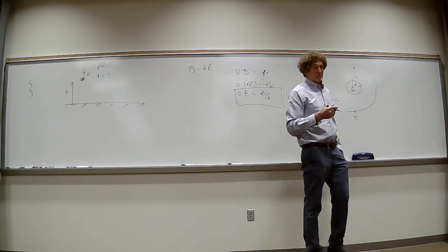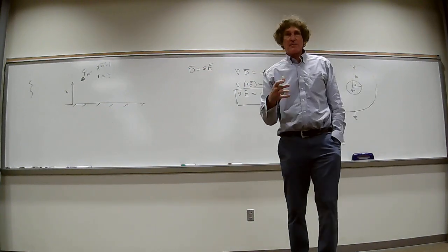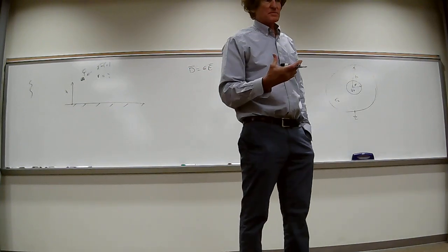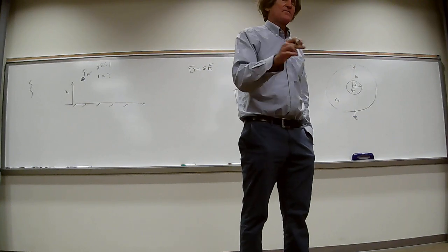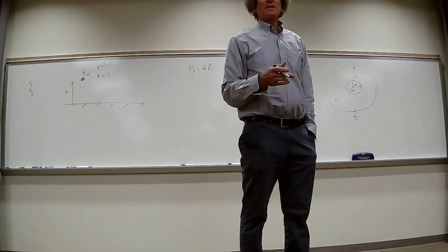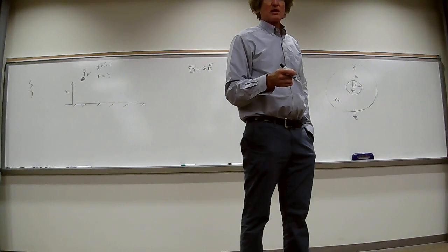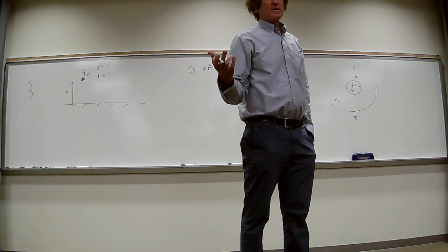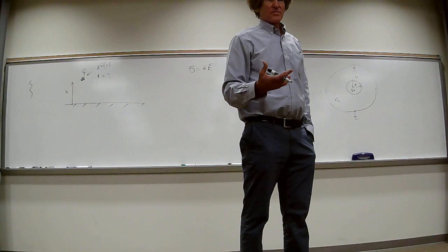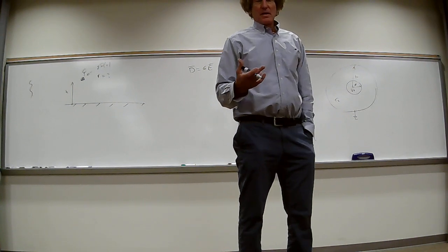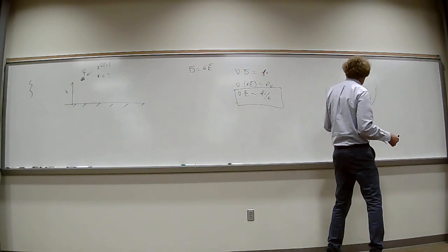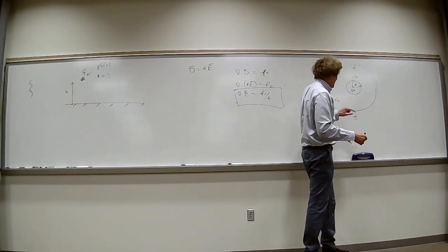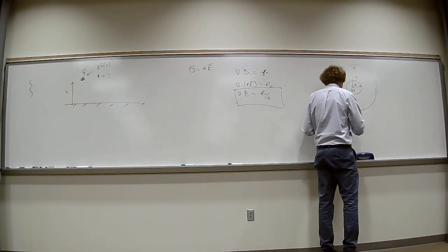Remember before we used to always assume a charge. Remember how we find capacitance for those problems? You assume a charge, then you get the D field, then you get the E field, then you integrate the thing and you find the voltage difference between the plates, and lo and behold, from that you find the capacitance as Q over V. And that works. But this is going at it in a different way. I'm saying the potential here is V naught, and this potential would be 0 volts.